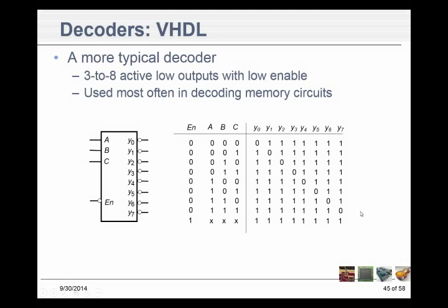Okay? So this is real useful for having 8 banks of memory out there, let's say all with 2K. I'm looking at some old EEPROMs that were 2K by 8. We needed not 2K, we needed 16K of ROM. So we used these decoders, and we used 8 of those 2K EEPROMs, and we would have our 3 address bits selecting which one of those chips we were going to turn on in 2K blocks.